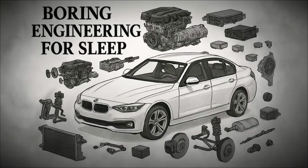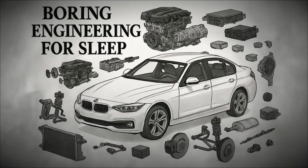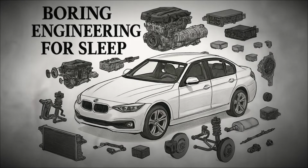One of the first of these components is often the catalytic converter, a device filled with a ceramic honeycomb coated with precious metals such as platinum, palladium, and rhodium. As exhaust gases pass through, chemical reactions occur that convert carbon monoxide into carbon dioxide, hydrocarbons into carbon dioxide and water, and nitrogen oxides into nitrogen and oxygen. This drastically reduces the toxicity of emissions and is one of the most important innovations in automotive engineering.